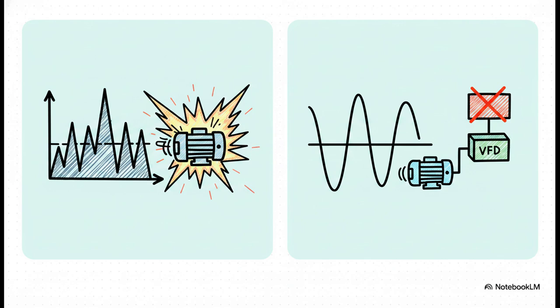To really get why this is such a game changer, just look at the stark contrast between the old way of doing things and using the VFD's internal PID. A system without PID is, well, it's basically blind. It's just banging on and off at full speed. Think of an air compressor that runs at 100% until it hits max pressure, violently shuts off, and then turns back on the second pressure drops. That wastes a massive amount of energy, and it absolutely tears apart your mechanical components.